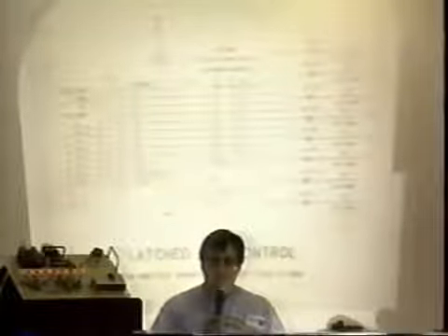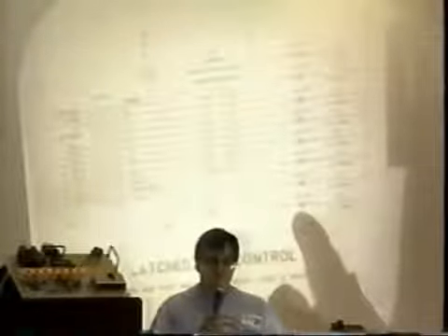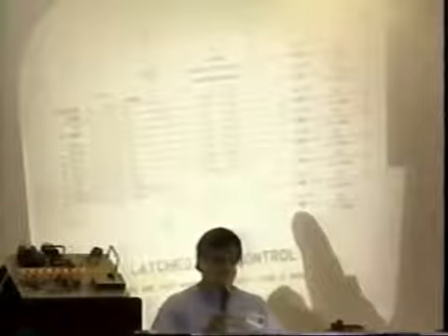So we have to light them up. Well, let's see. If I send numbers out here, I can light them up. So if I send the number 1, the first LED will light up. If I send the number 2, the second one will light up. And if I send a 3, both of them will light up. How come both of them will light up with 3? It's binary. We're sending binary.